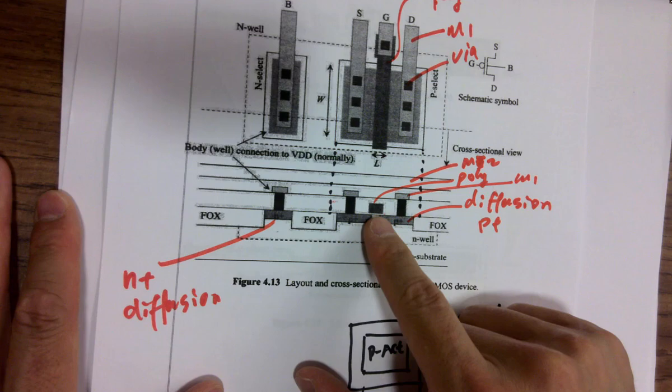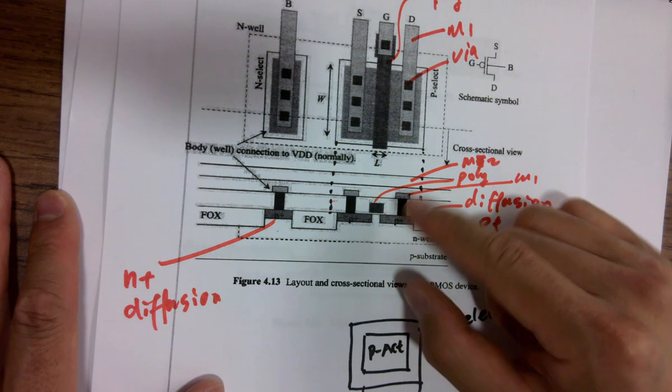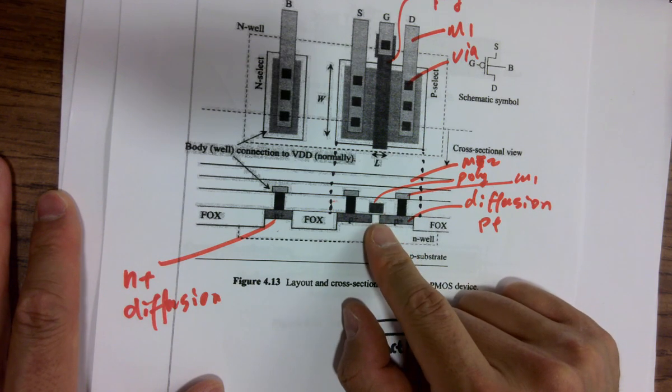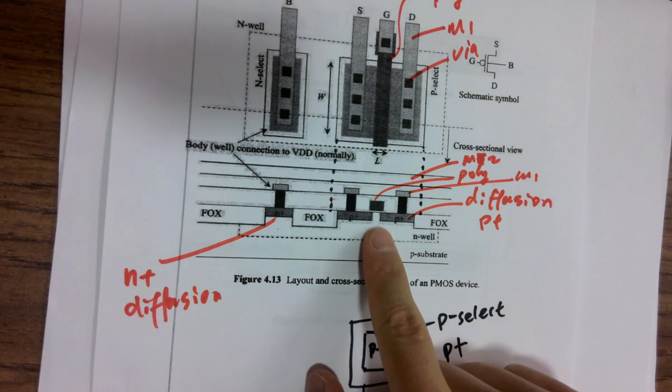So in that case, you put the poly here first, and then you start doping the area. Because this is blocking this gap, it's going to directly leave a gap or opening underneath the poly. Exactly. Does that make sense? So you have something on the top. It's like an umbrella on top. When it rains on top of the umbrella, it doesn't get whatever is underneath it.